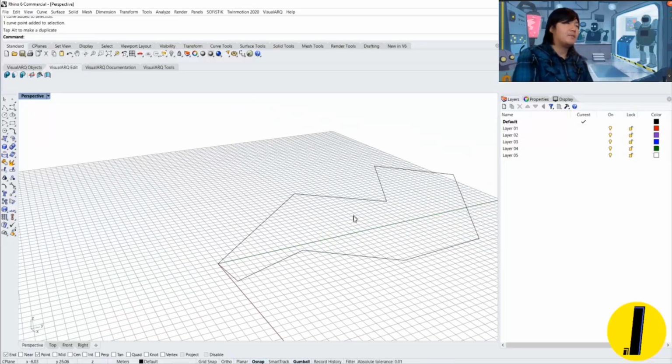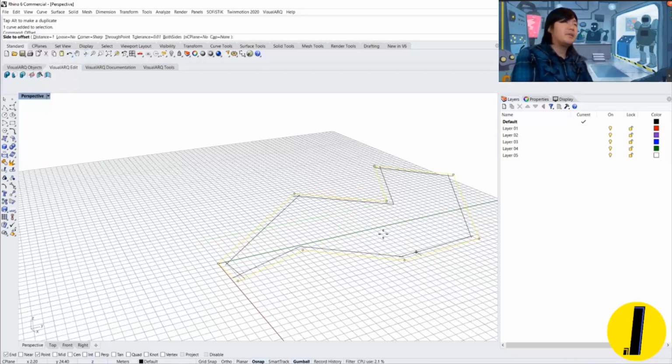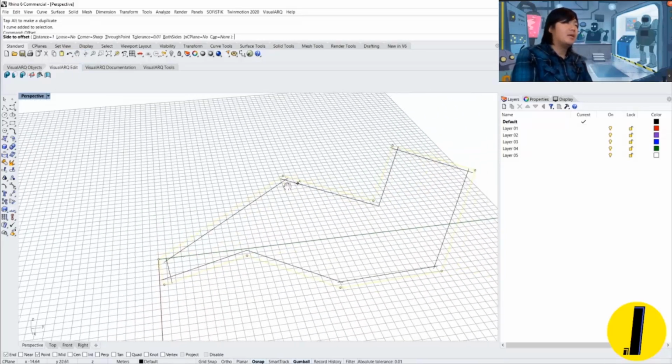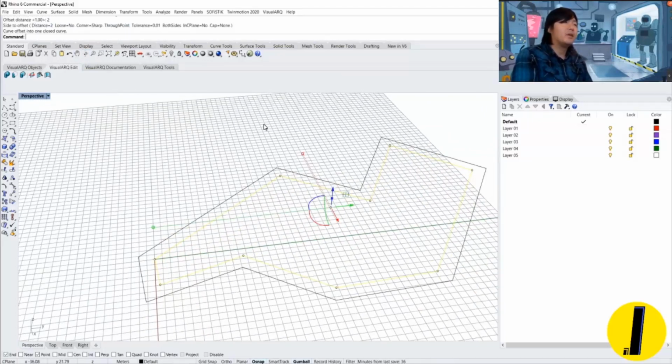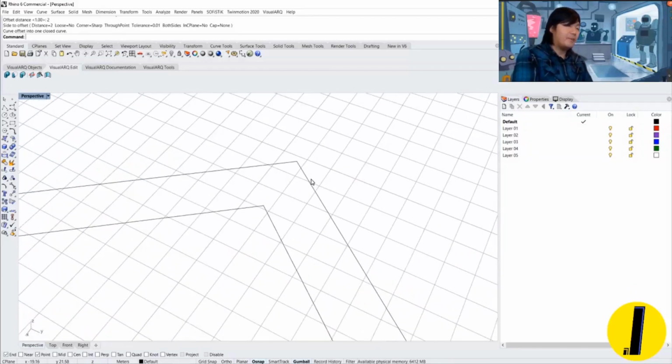And for all the commands, instead of clicking here, you can type commands in the command tab here. For example, if I want to do offset, it's the same as the AutoCAD command. You can offset, give the distance value in meters, and click the inner side or outer side of the boundary, then you get the offset. So all the commands are the same.